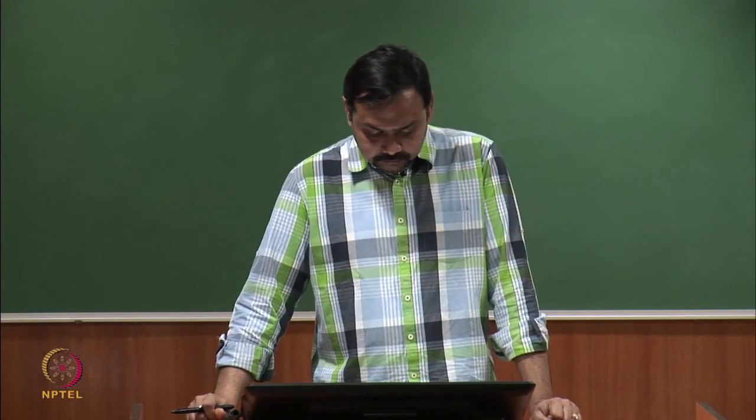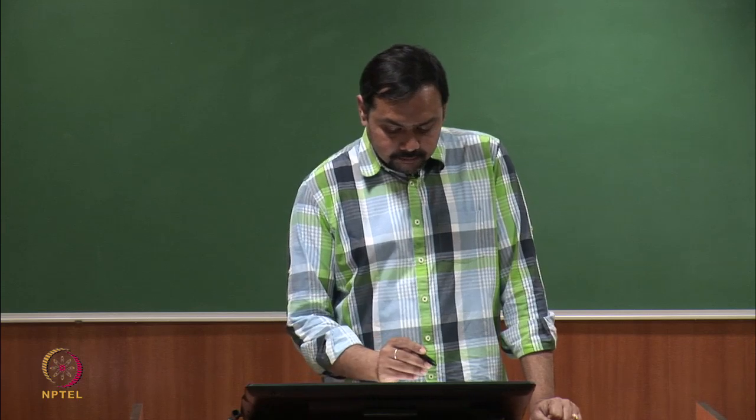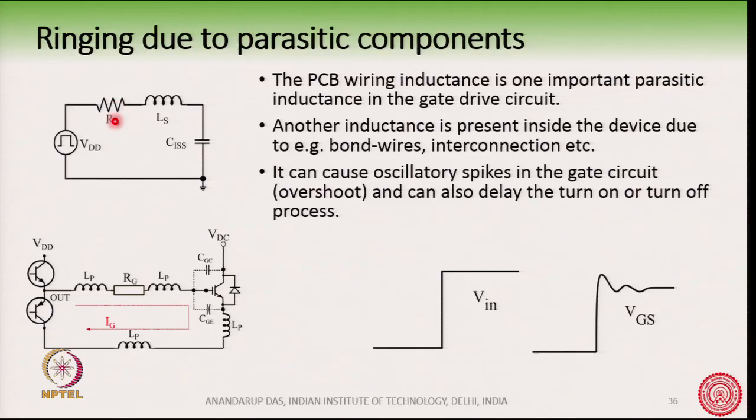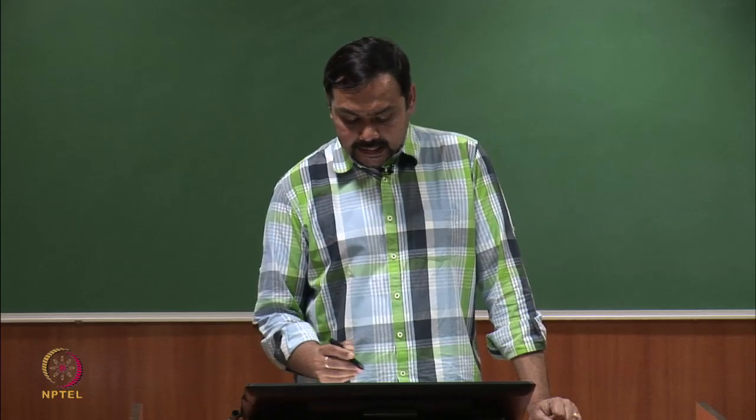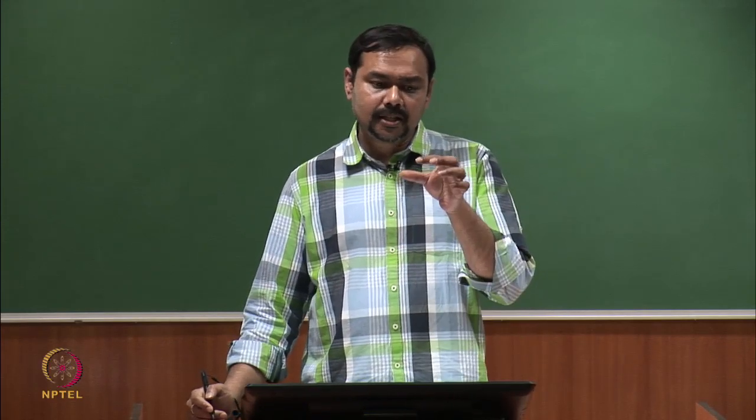Although so far we have not talked about any inductance in the circuit, actually all these circuits have inductances. Where are the inductances? Number 1, there is a PCB wiring inductance, because the gate driver circuit is on a PCB, whereas the power device is away from the gate driver circuit.